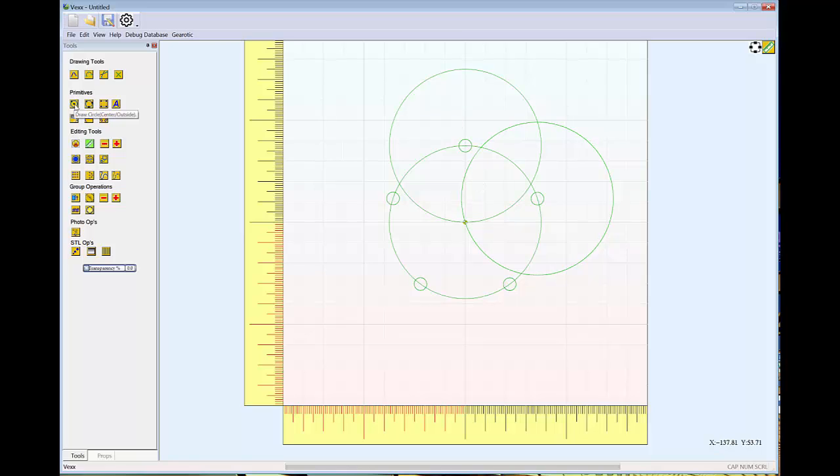So I'm going to draw another circle, centered at 0, and about 6.5 millimeters above the center, or above the top of, this swivel point. So somewhere around here. It's not important exactly how far, but this is going to create your swivel circle. So now we can see our vane is this shape here, the one side of one circle, and this shape here, which is the other side of the first circle.